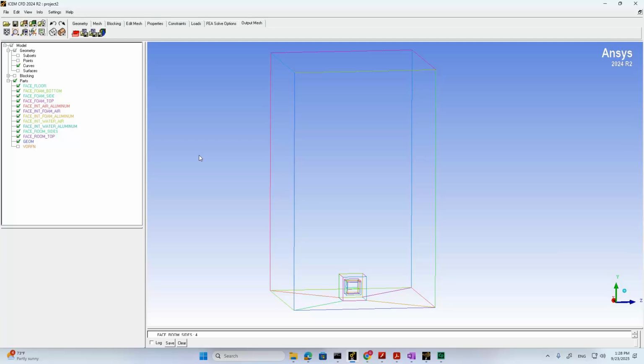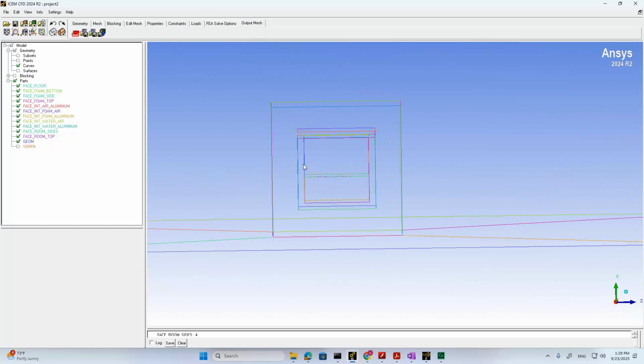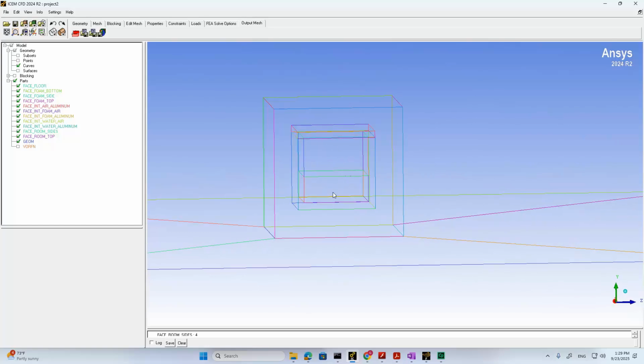So the third thing we have to provide to Fluent is zones. Okay, because in different places we have different materials, right? In this room we have air, in this cooler we have insulation first, then when we get into the cooler we have aluminum container, then we have some more air inside the container and some water here, right?